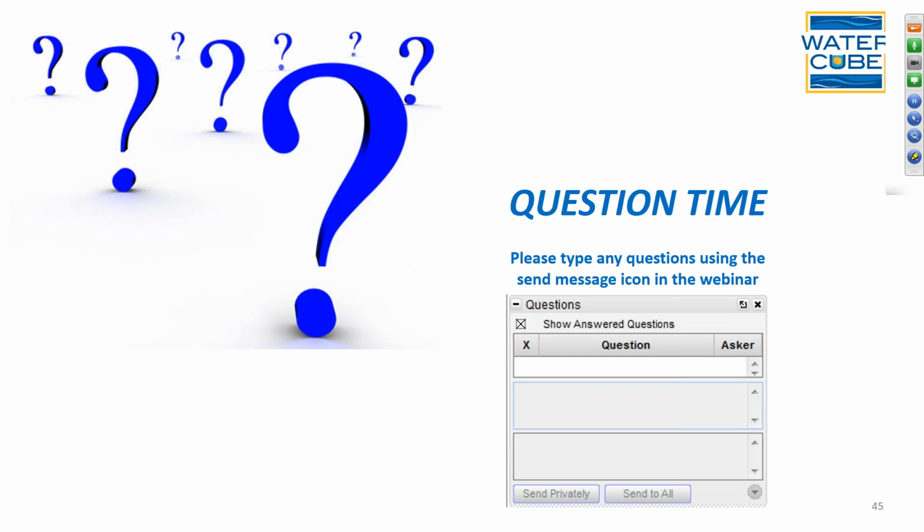And again, with LiDAR tying that in. I don't know if you want to mention that from a bathymetric standpoint for tying it all together. Yeah, well, we use LiDAR, again, it's most useful when you're trying to understand floodplains. It's obviously a lot of data, but when we stitch all of that data together, the LiDAR data also is quite helpful for determining a particular boundary interface between where the water is and where the land surface is for that flow.